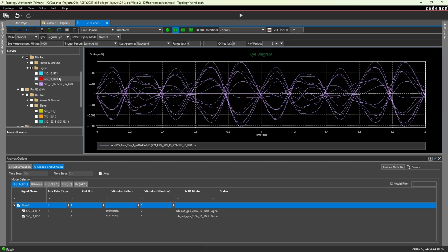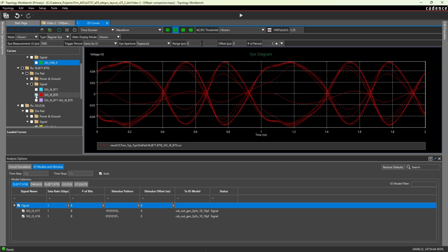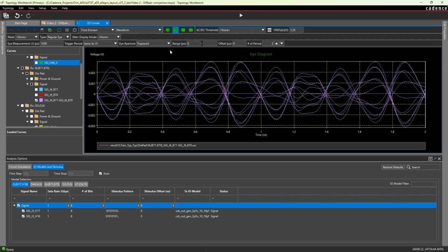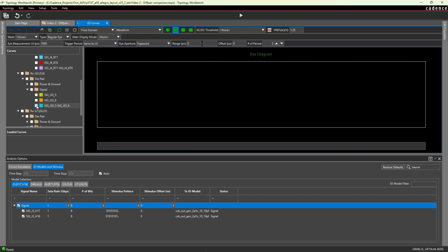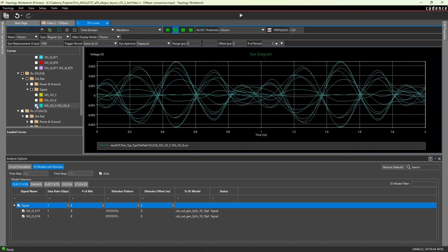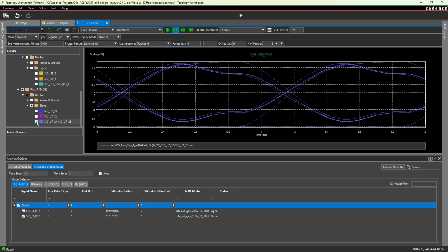We have the eye diagram for the J6 connector. It doesn't seem to handle its differential signaling too well at 1 gigahertz. So that may need to be looked at if you want to push 1 gigahertz through there, but it's not intended to handle that. And then here we have J33, similar situation, it's to be expected. Now for our U7 chip, it's designed specifically to handle up to 1 gigahertz and likely beyond.